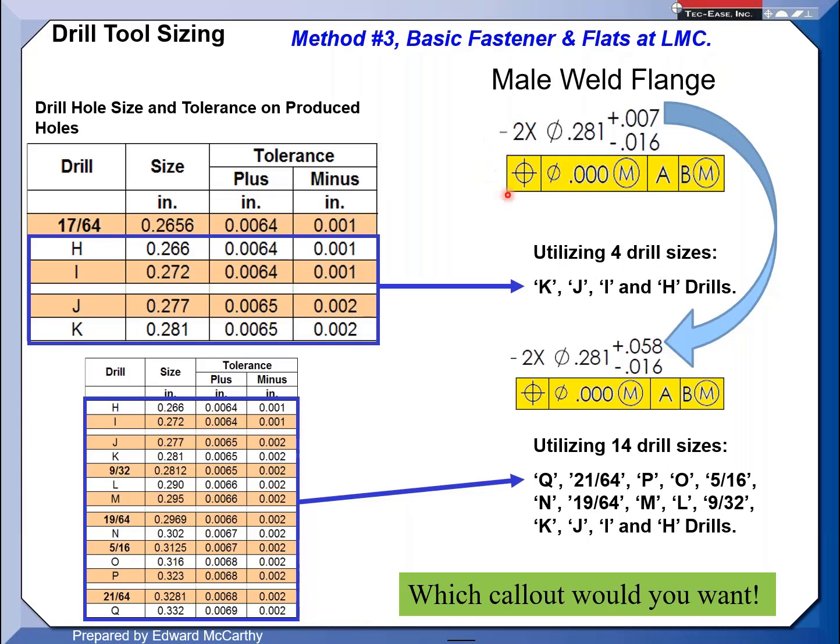In this case, somebody was creative and came in and actually converted it from what we call a directly toleranced dimension. They made the value basic 281, and they redistributed this tolerance into an unequal bilateral profile. In that case, their results gave me the same effect as what we're stepping through here in position.